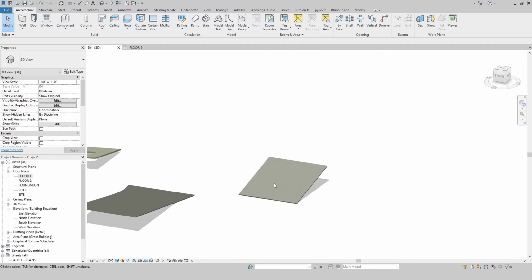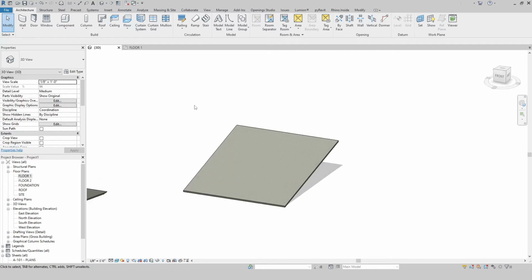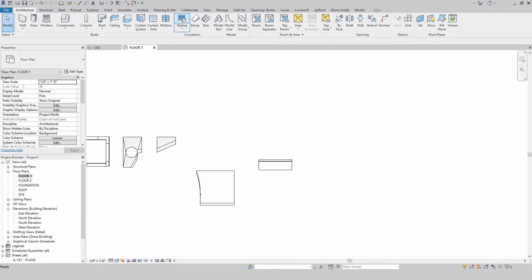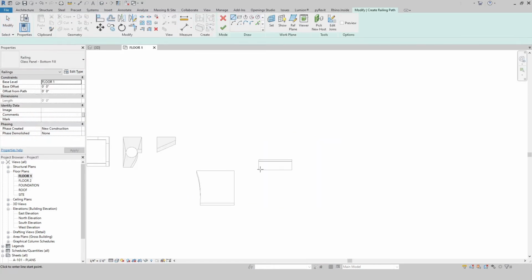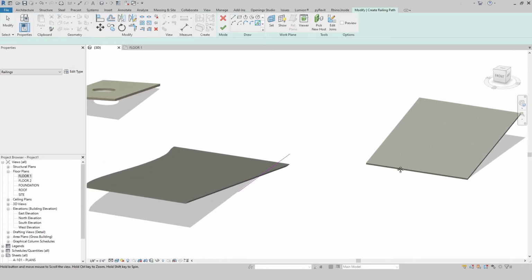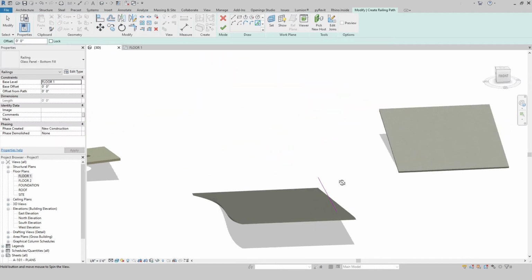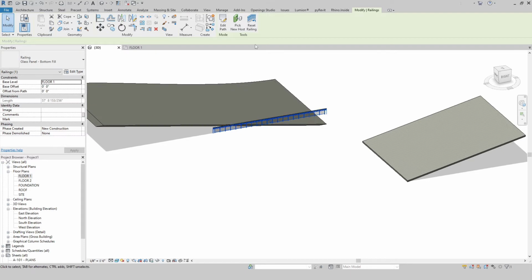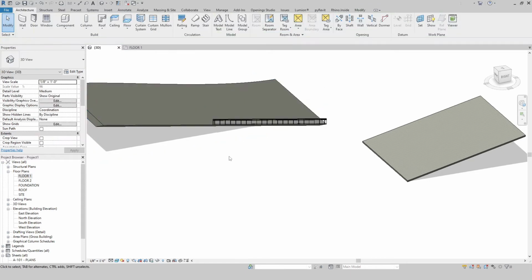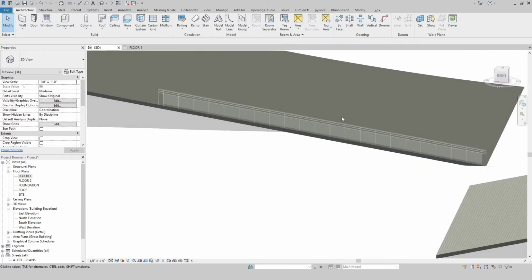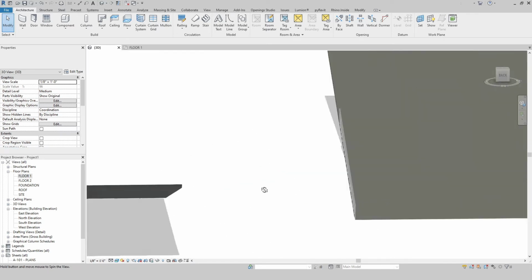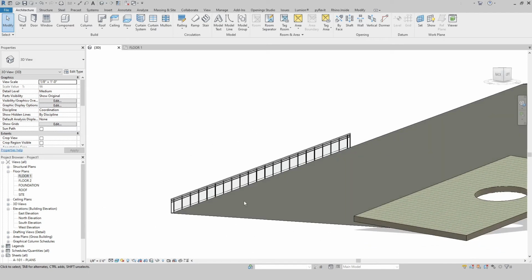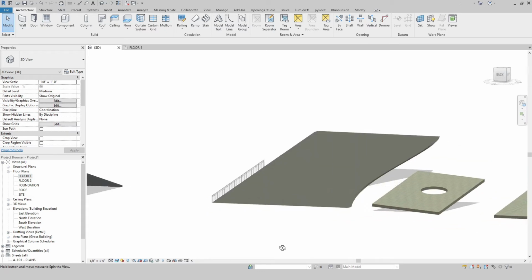And then from here, let's say you want to put a railing on this just real quick. If I do a railing sketch, pick the edge right here in 3D. Let's see what I'm doing. Right, so I pick that edge, and then I'm going to say, okay, this ramp lives right here, but I can pick a host of this, and now it applies it. So this becomes much more of a workable ramp now, which is kind of cool.